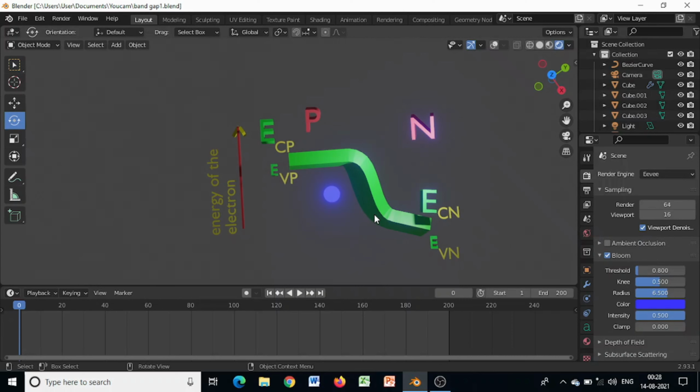The condition that the barrier be less than 100 angstrom or 1000 angstrom thick is a necessary but not a sufficient condition for tunneling of an electron from the p side valence band to the n side conduction band.